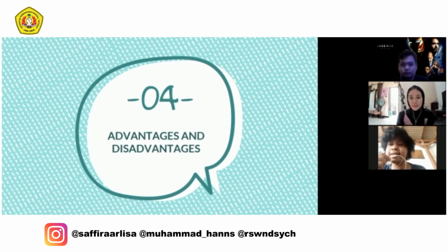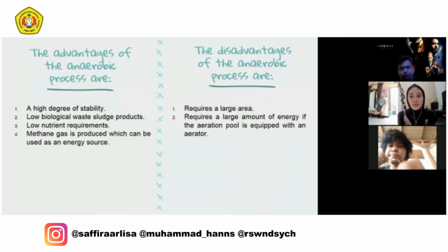Advantage and disadvantage. Next, the advantages of the anaerobic process are: 1. A high degree of stability. 2. Low biological waste sludge production. 3. Low nutrient requirements. 4. Methane gas is produced, which can be used as an energy source.